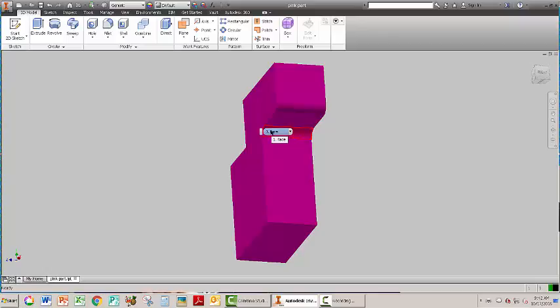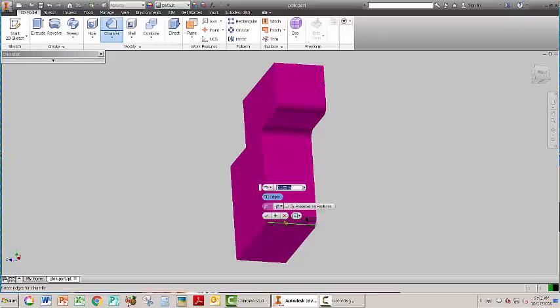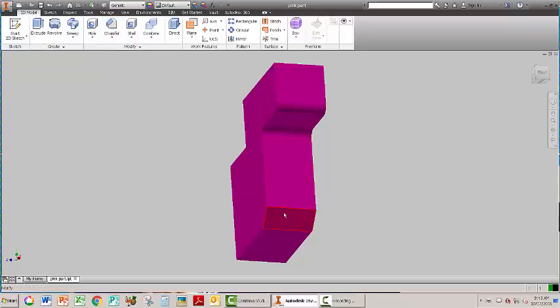I can do these same options with my chamfer tool here. In this case, it wants to know what distance to set the edge at. Let's make it a pretty big edge here, and it's going to take a chunk off of that corner. Again, editing it is just as simple as selecting it, opening up the editing queue, and we can make additional edits to it.